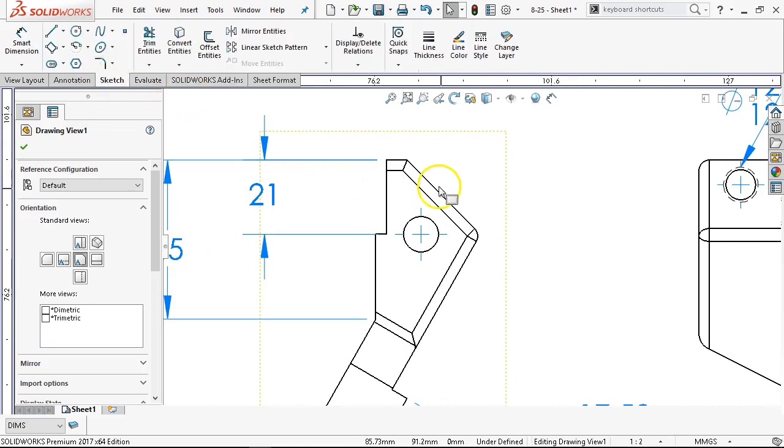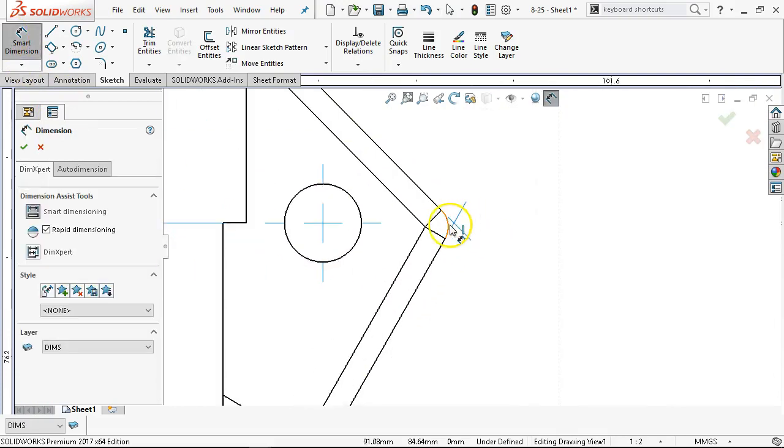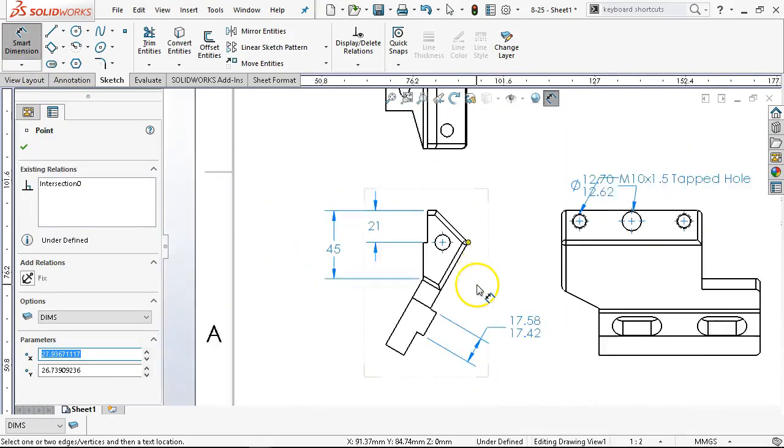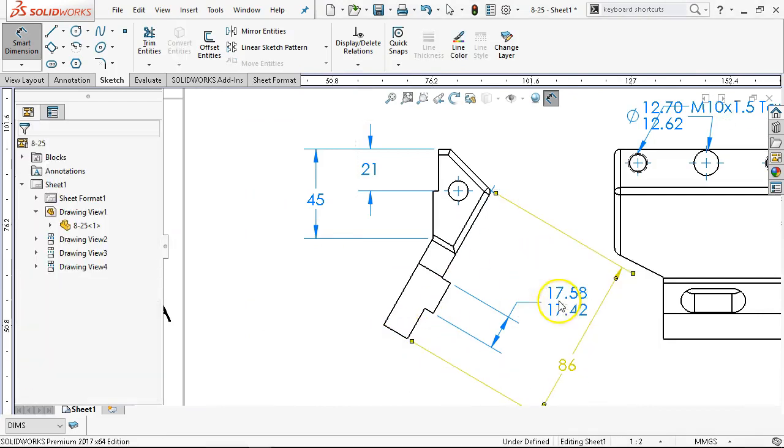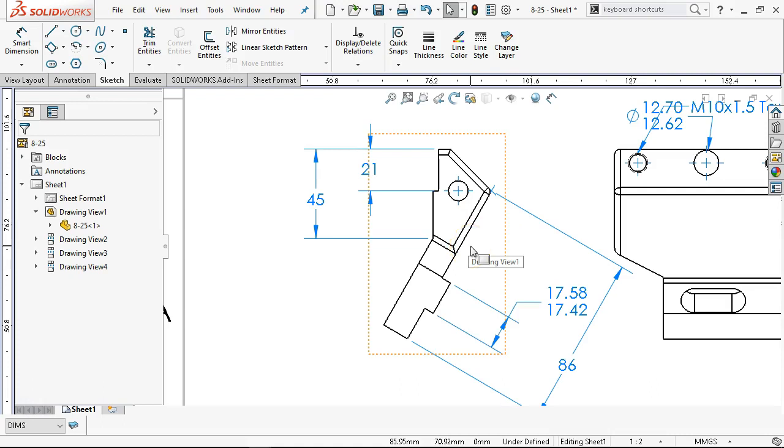it. On the sketch then, if I go for an intersection, alright, so that virtual sharp will give me the point where those two edges intersect, and then we can pull the dimension back. Alright, so 51, yeah, that was still to the center line.